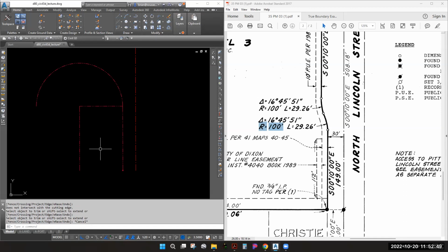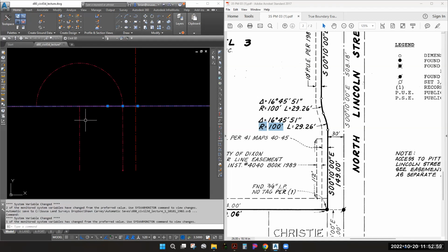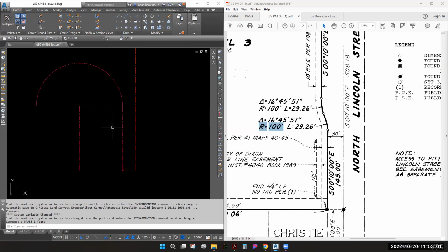So edge mode on is always a wonderful thing because you don't have to physically draw a construction line so that you can trim something out and then have to delete that construction line. So hopefully that makes sense. Review that part of the recording should you need, okay?